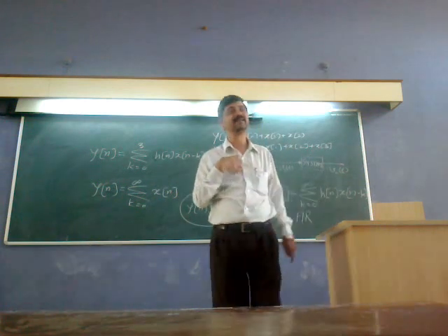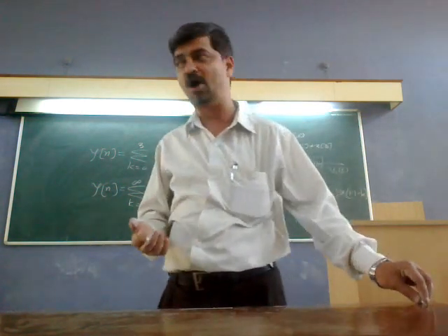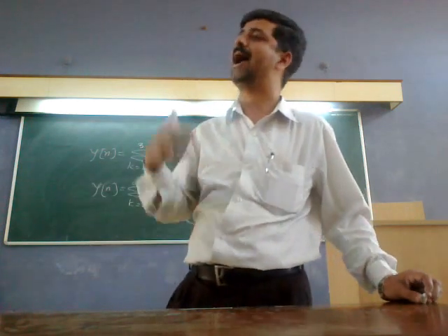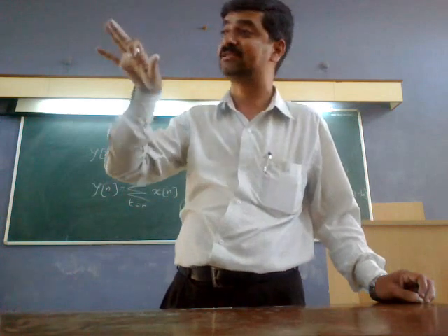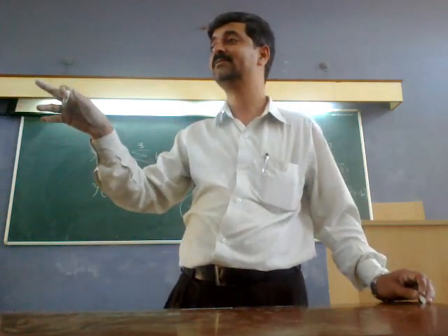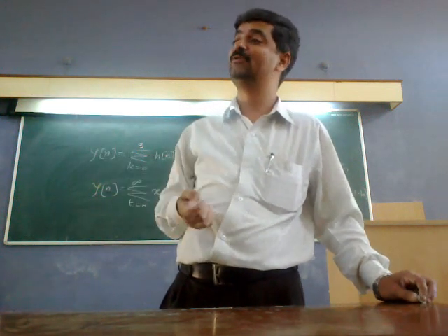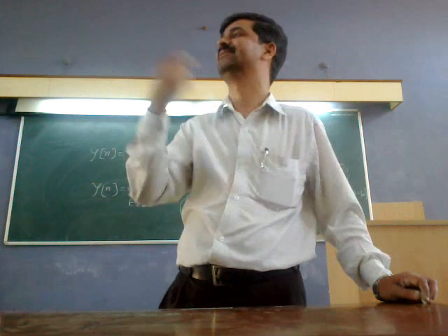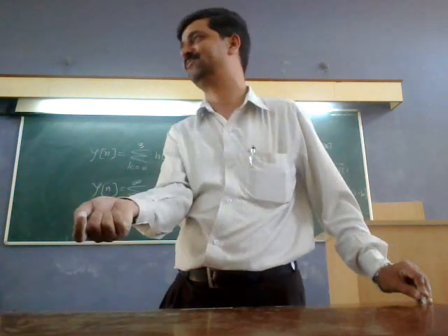So I can have a system which depends on current and previous inputs and some past outputs. It can't depend on the current output, because then it would not be instantly responding, it would be infinite looping; unless the output is produced, it can't depend on itself.